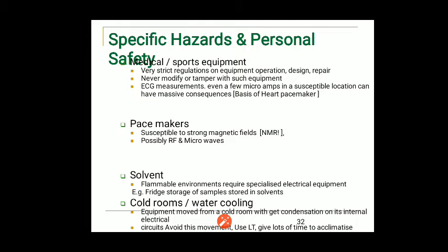Never modify or tamper with such equipment. For ECG measurements, even a few microamperes in susceptible locations can have massive consequences for the heart. Next are pacemakers.